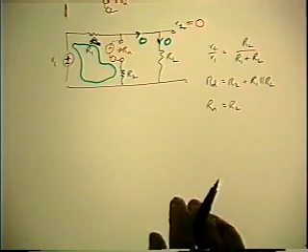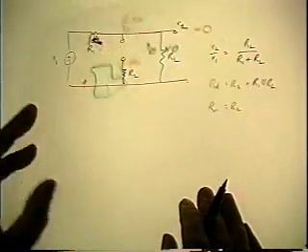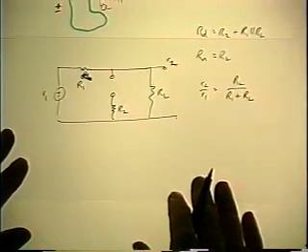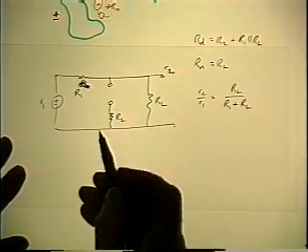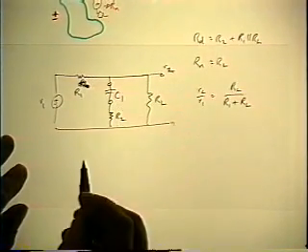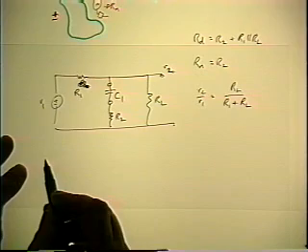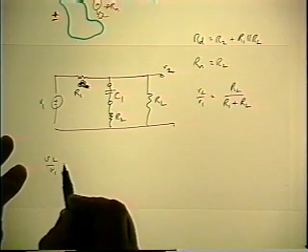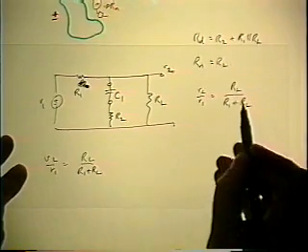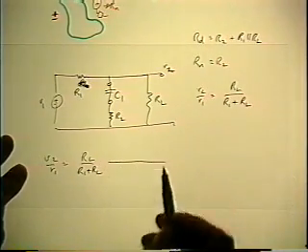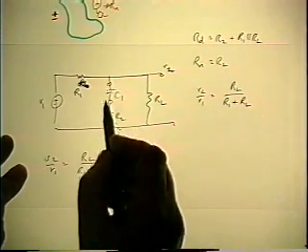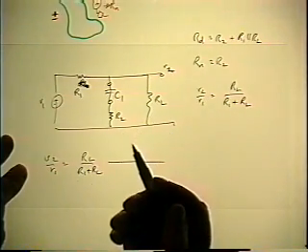Okay, that's almost the answer now. All that's left is to put the capacitor back in and use the theorem. So the theorem says V2 over V1 is the reference gain, RL over R1 plus RL, multiplied by the correction factor for a parallel element, parallel because the reference value was infinite.